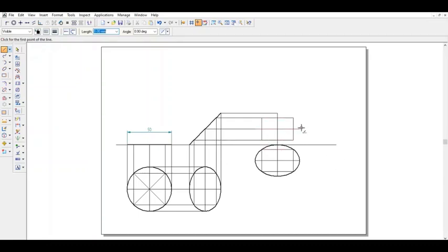Now how to draw this? All the 8 points are here, but again go for ellipse by 3 points. I know this particular line is here. You can either select this particular line or this particular line. Any of the axis you have to select first. Suppose I am selecting this one, it is difficult for me to go for this, I don't know where the end point is.